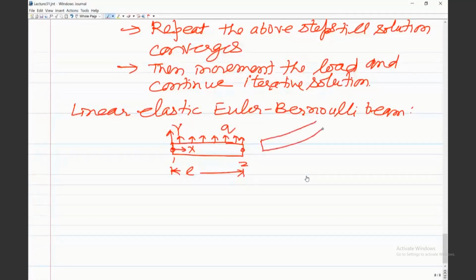this deformed element is, let us say, like this. This is the center line, and if we take any line element, let us say this line element, so this line element goes over here. This was the original configuration of that line element. And now if you see the center point of this line element, which was here, it gets displaced by an amount u naught.